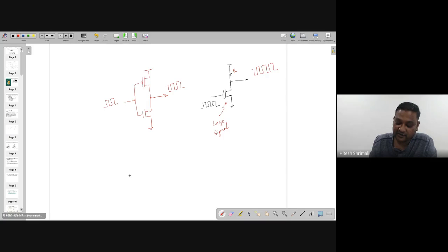But we are not going into that, like class A, B, and all these inverter names. For the common source amplifier with different loads, you can achieve the same characteristic here, and the same characteristic here also. If I am using a current source as a load, let's assume this is Vbias and this is Vin, which is a square wave, the output will be the inverted one, right?